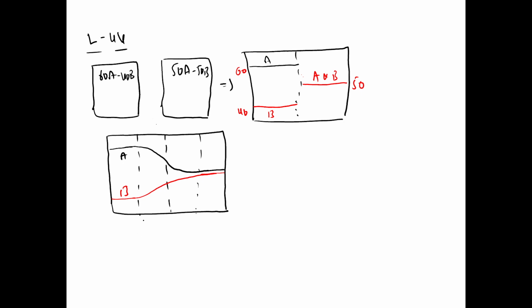From this concentration profile itself you will get more outputs. This is the diffusion depth for a component in the concentration versus X graph. This is the diffusion depth, and this is the Matano plane, X naught, or mass balancing plane. Similarly, we will be determining the interdiffusion coefficients, and the fluxes are very easy.